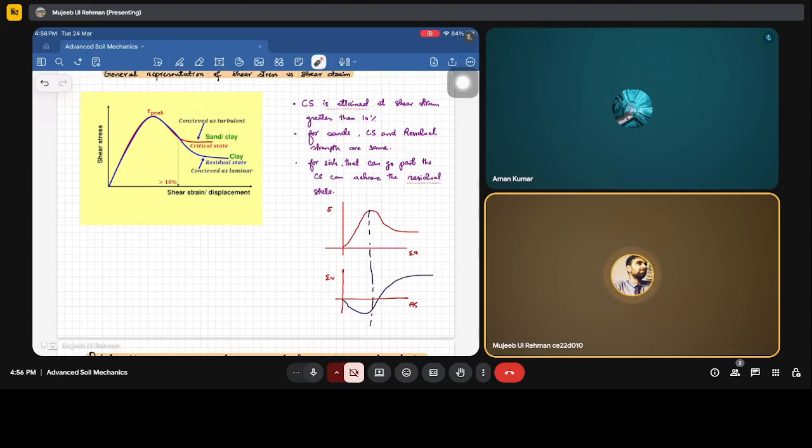So at a constant deviatoric stress and constant volumetric strain, there is accumulation of plastic strain, and this occurs due to the reconsolidation or rearrangements in the sample, which is bringing this accumulation of plastic strain in the sample, and this state is called the critical state. After which there will be no change in the deviatoric stress, effective stress, or volumetric strain.